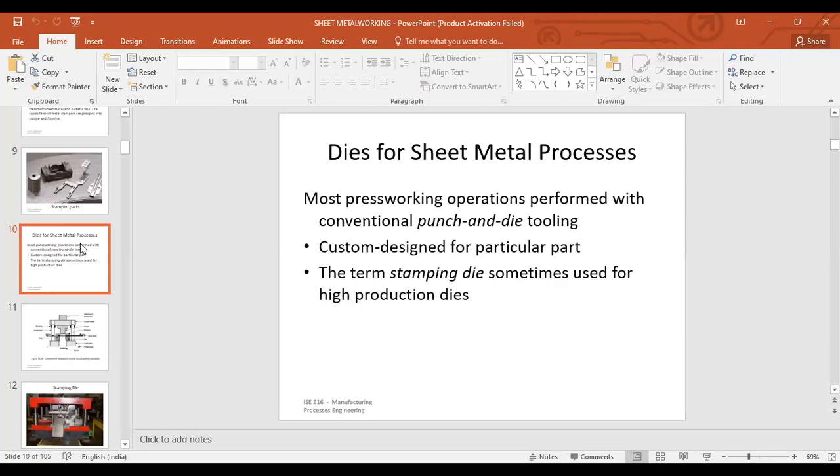That is usually the case, but other cases are where you have a single press and you just change the punch and die setup, right? Basically batch production, you can call it, where you change the die and setup for each part that you want to produce. So for 10 components of one part, you will fit that die and punch in that general equipment and produce maybe 10 components, and then for another component with another design, the die and punch have to be changed. You change the die and punch, suiting that particular component.